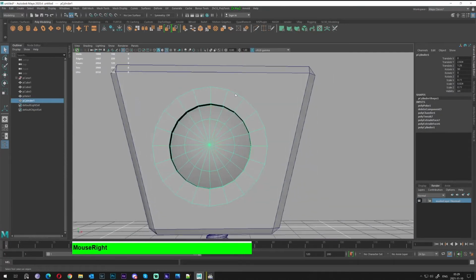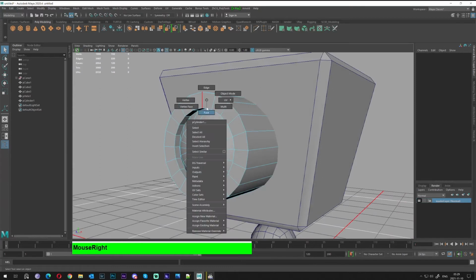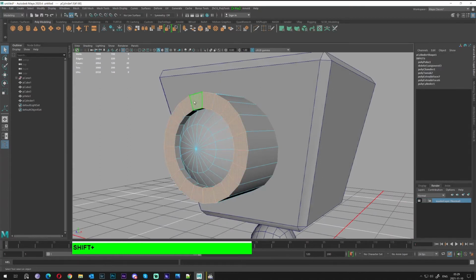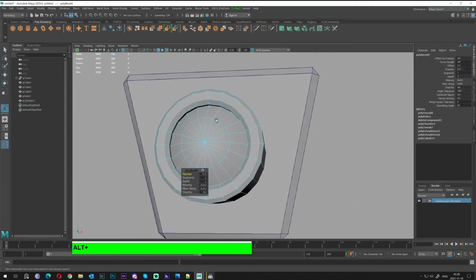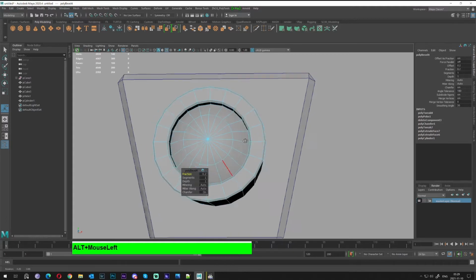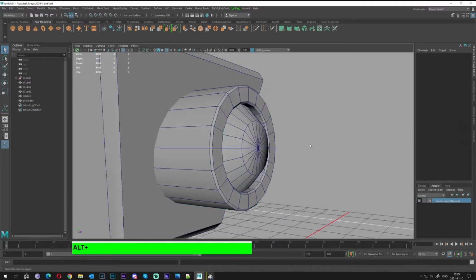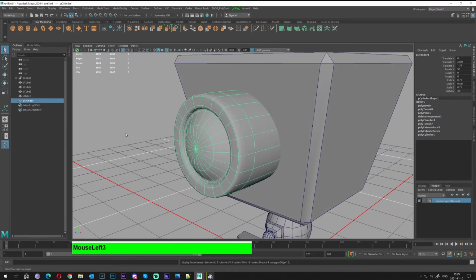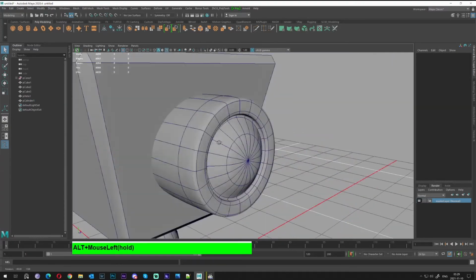Great, so what we can do next, we can add, let's say, bevel lines. So I will select the ring, go to edges, edge perimeter, Ctrl B in order to bevel. Probably I will shrink it to 0.2. Great, something like that.